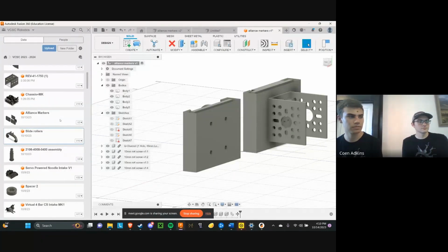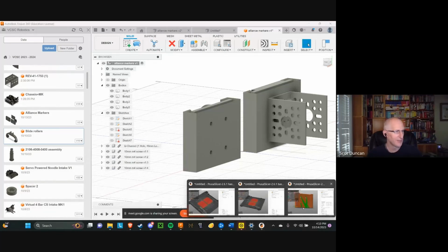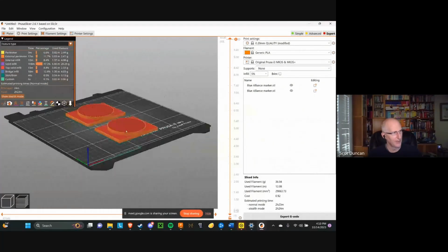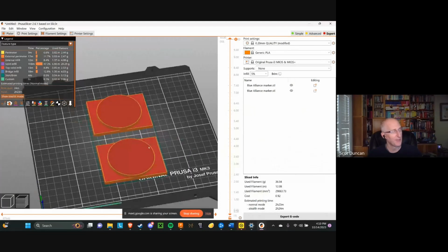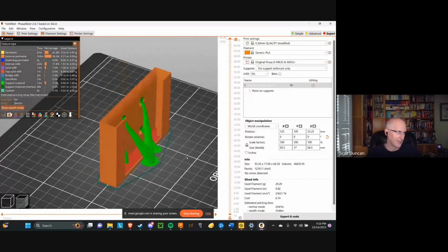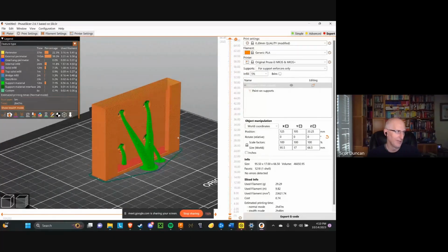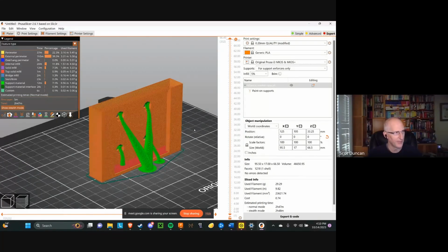I apologize if I missed it, but on the 3D printing, I didn't recall, did it decide the orientation automatically, or do you have advice on deciding the orientation? I assume when you were printing that, you printed it upright because that was the orientation where the least amount would need to be supported. For instance, if you printed it flat, then both those sides would be overhangs, hanging in free space. So by printing it vertically like that, it would not require as much support, or as you point out, maybe no support. Is that how you decide which orientation you're going to use to print a 3D object?